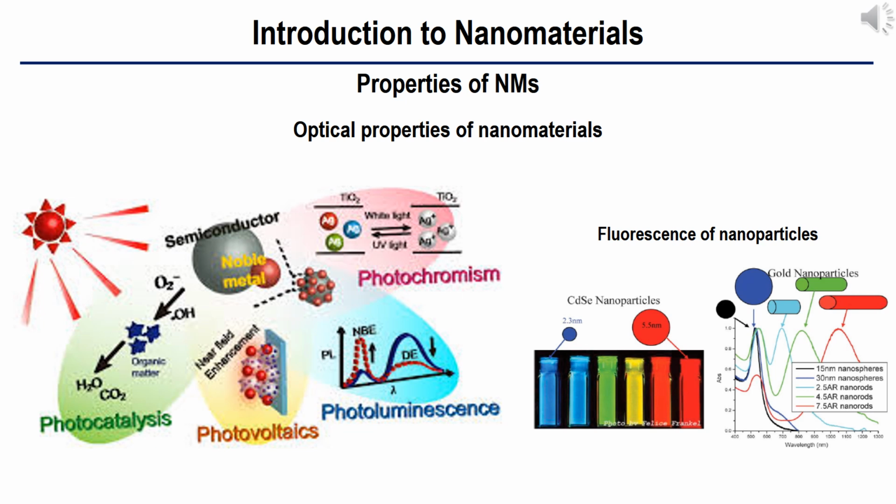Reduced imperfections are also an important factor in determination of the properties of nanomaterials. Nanostructures and nanomaterials favor a self-purification process in that the impurities and intrinsic material defects will move to near the surface upon thermal annealing. This increased material perfection affects the properties of nanomaterials. For example, the chemical stability for certain nanomaterials may be enhanced, and the mechanical properties of nanomaterials will be better than the bulk materials. The superior mechanical properties of carbon nanotubes are well known.